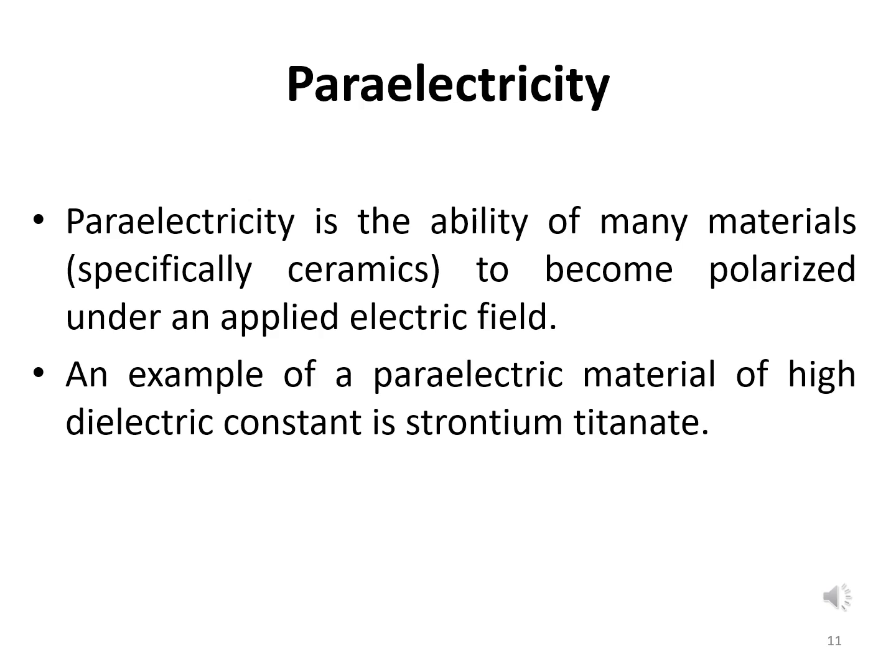So this can happen even if there is no permanent electric dipole, as happens in ferroelectricity, that exists in the material, and the removal of the field results in the polarization in that material returning to zero. So mechanisms that cause paraelectric behavior are distortion of individual ions, displacement of the electron cloud from the nucleus, and the polarization of molecules or combination of ions or defects.